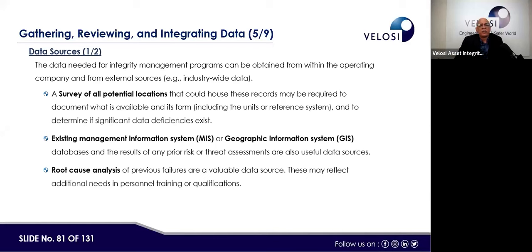So the information comes first from the engineering side, then fabrication records, QA/QC records, NDT records. Then in operation, there could be operational logs and control room SCADA logs. Then there would be inspections, and there could be some failures and incidents, the event logs as we call them, inspection planning and execution, maintenance planning and execution. All this information comes from various sources and various departments, which we need to use for our day-to-day work.